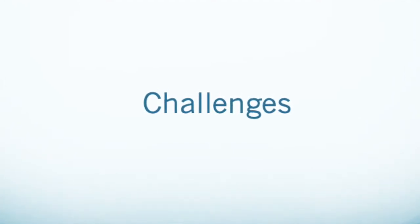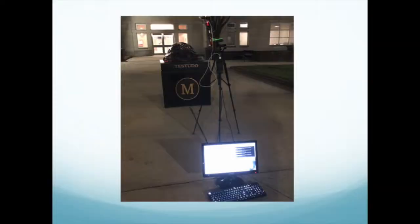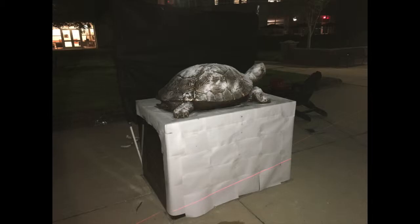I encountered several challenges when doing this project, the first of which came from the physical nature of the statue itself. The base of the statue is black, and the statue itself is dark copper. This means that the laser light did not reflect very well. In order to overcome this, I went back out into the field and covered the base with white printer paper and Testudo with baking soda in an attempt to increase the reflectivity of the surface.